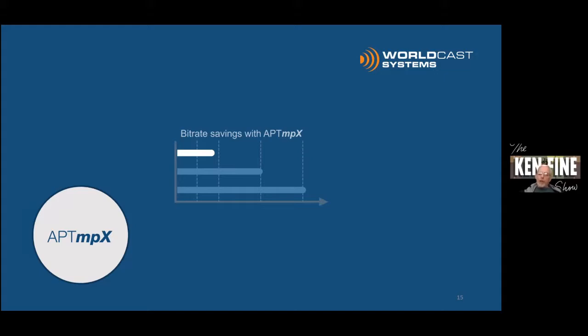So would you lose separation as well as possibly RDS? No, because the composite signal is being sampled as a whole. You've got the whole composite, which is essentially an analog signal. MPX over IP is sampling that analog signal, which includes the left plus right, left minus right, pilot, RDS. All that comes in the composite, and that gets sampled. What you're losing with the lower bit rate or the lower sample rate is the precision of that sample. So in cases where the modulation is varying widely, the composite signal has a wide swing, it's not going to be as smooth a transition. It's not going to match the analog signal as closely as it would with a 24-bit sample.